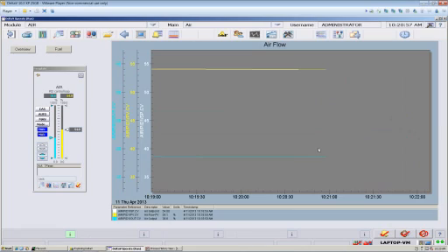Now all these tests can be done. You could do this with paper strip chart recorders and stopwatches and rulers. If you were tuning a pneumatic controller in one of your plants, you can still use the Lambda method to tune those older simple controllers. The thing is, if you have a nice charting tool like this, it makes life so much easier. At the click of a mouse, you can measure what your output, what your timestamp, and what your PV are.